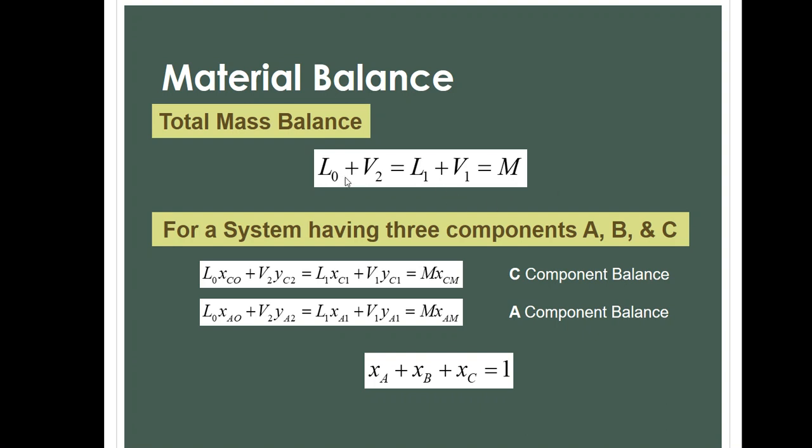So you multiply the L's with the mole fraction in the liquid phase, X, and you multiply the V's with the mole fraction in the gas phase, which are the Y. So we label them as, in this case, X_A0. The 0 here is because it's the mole fraction of the liquid that enters the column, your solvent, so X_A0. The numbers that appear are all the same when we pair them up. I'm referring to the stream and the concentration by which it is being multiplied.